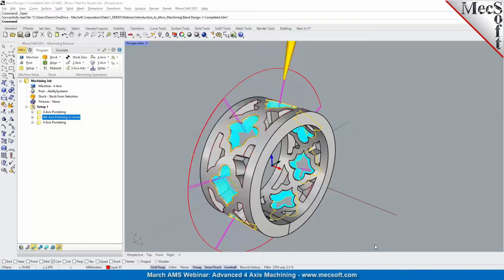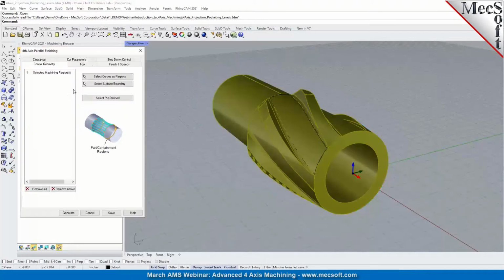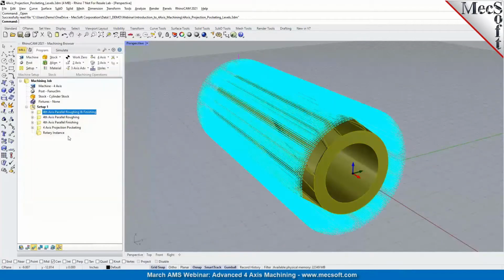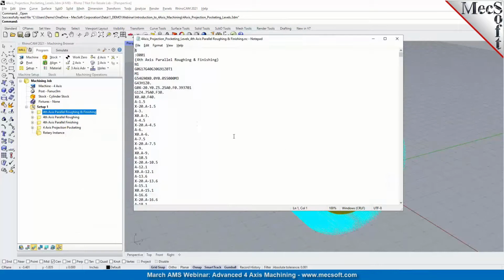So we have an option. When you post-process these toolpaths, they're basically output as units per minute. That's the default output. So when I go ahead and do a post-process, let's say we want to take one of these operations in here and do a post. The feed rate is output in whatever the program feed rate is, which is units per minute.